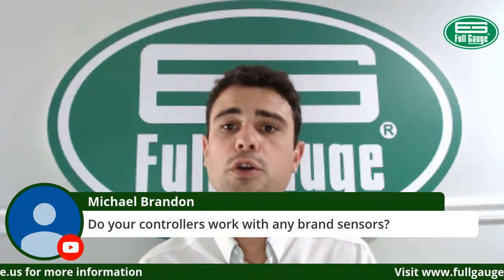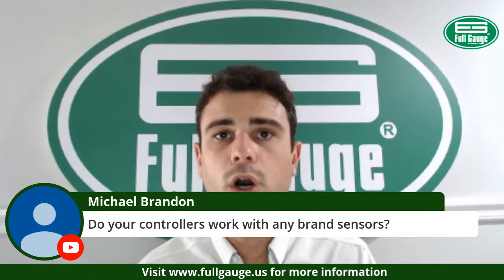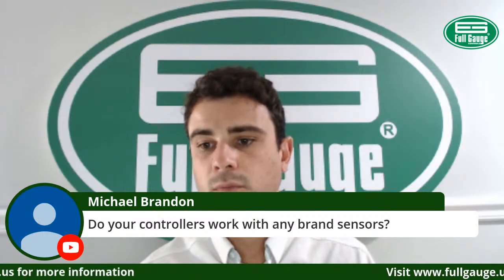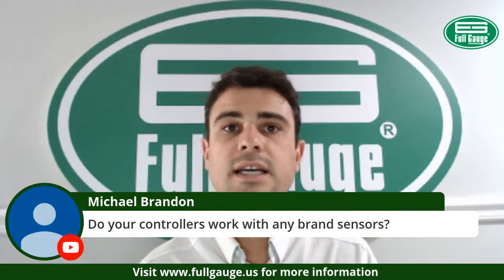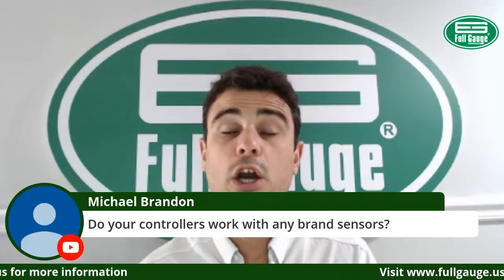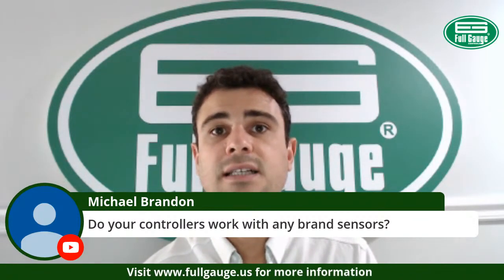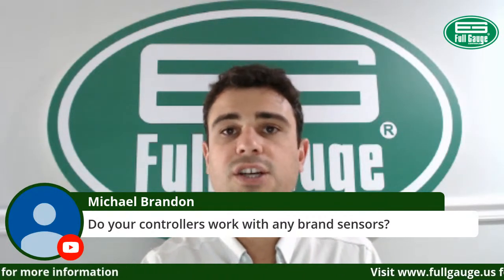But if you do connect a different sensor manufacturer to our controller, it will work. However, you might have some temperature difference in the range, so the recommendation is to use the offset function to calibrate that deviation created by changing the sensor.